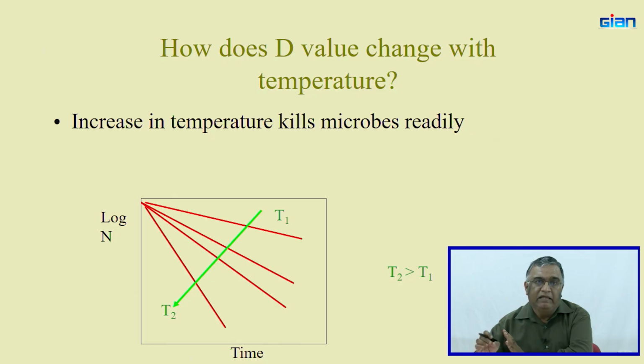So normally, it's a known fact in the industry that high temperature short time is better, because the higher the temperature, the more quickly you inactivate the bacteria with less time. At the same time, a lot of the nutrients are heat stable, so at higher temperature it may not affect the nutrients that much. So you may still have a nutritious product, but less in terms of microorganisms.